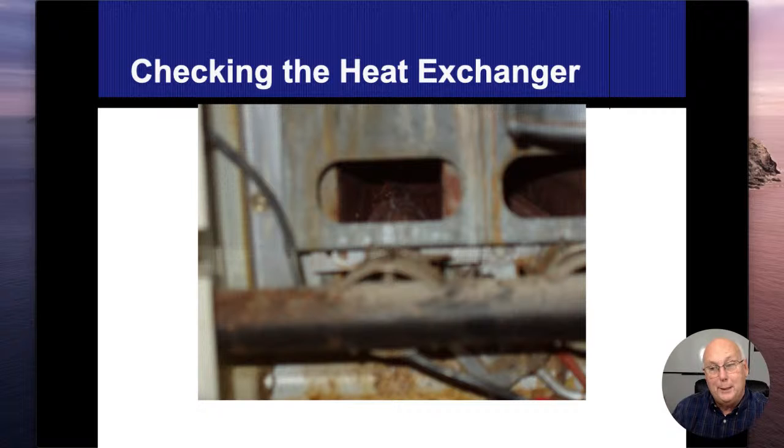If it's so bad that we're getting carbon monoxide leaking into the house, then hopefully you'll be picking it up that way. But small openings, small cracks, which are still dangerous, they're not going to bleed over into the circulation air because of those pressure differentials. But it's still a dangerous seal. So here's a natural draft one. You can see inside of it, it's rusty, it's dirty.